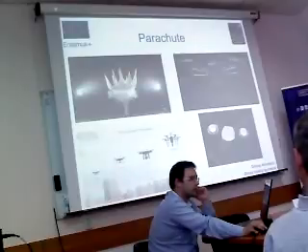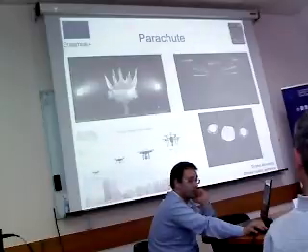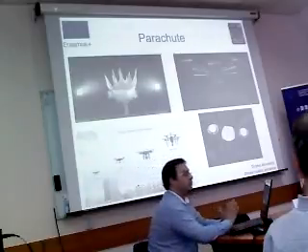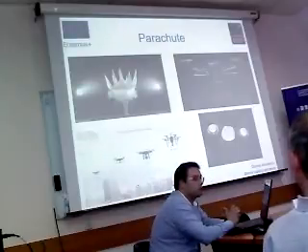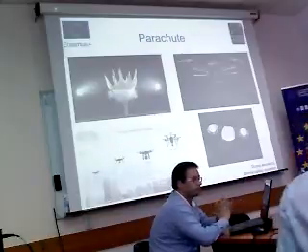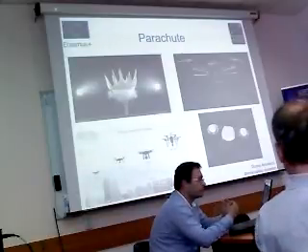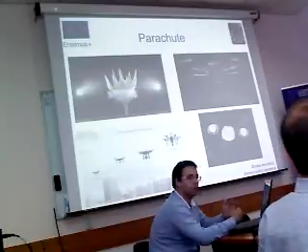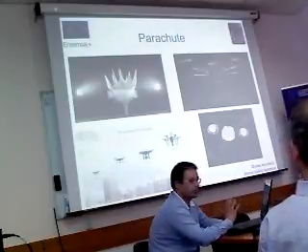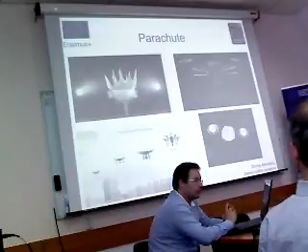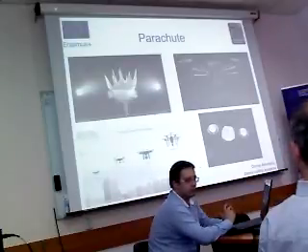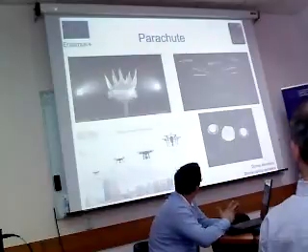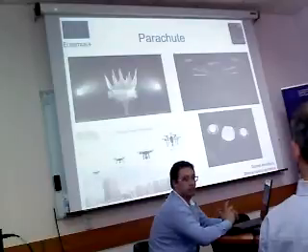This producer offers a reusable module, called SafeAir, which is suggested for compact units, for drones weighing 2 kilograms, and also for larger ones. Users of this system can customize the speed of the drop rate, between 3 and 6 meters per second, and it can also be activated at low altitude. So it looks like a perfect solution, especially in urban areas.